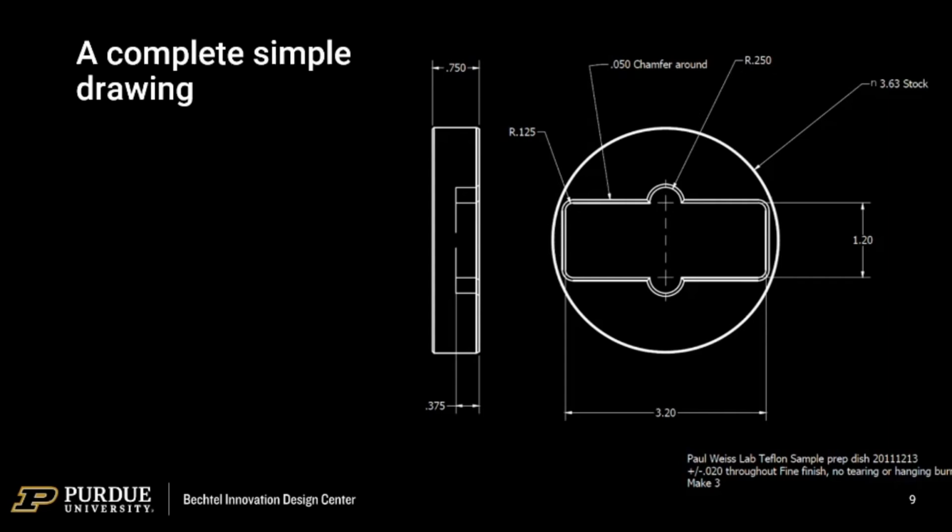So as you can see on the left there, I've got the full thickness I want. I describe the depth of the pocket that's in there. I give my machinist the stock on the side. So I say, I'm providing you this stock and it's this diameter. You don't need to do any machining operation. That's a great way to save a lot of money and time, is to machine out of stock on your first major dimension, which in this case would be the diameter of this rod.